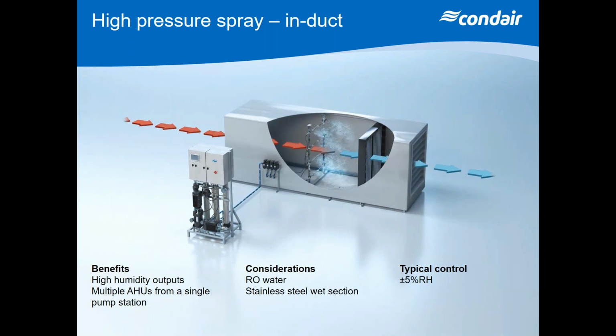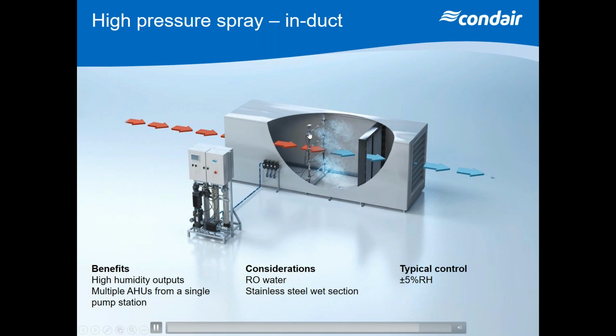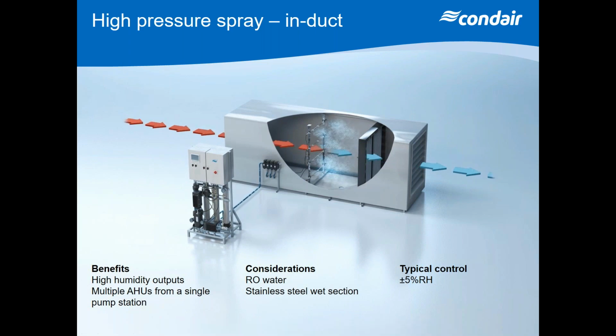We have to do that for two reasons. Firstly, if we don't, the nozzles that you're using will block up. And secondly, any minerals that get sprayed into the air handling unit will fall out into the air handling unit as the water changes its state from a liquid into a gas. So we have to use RO water.